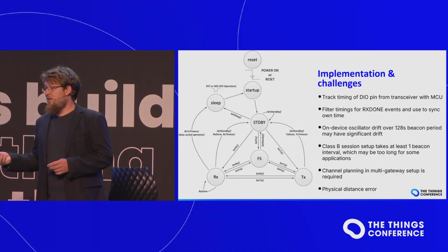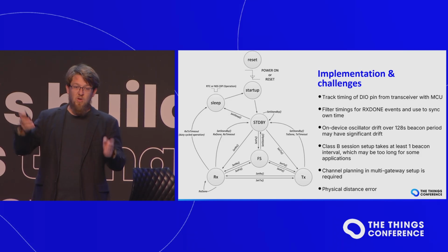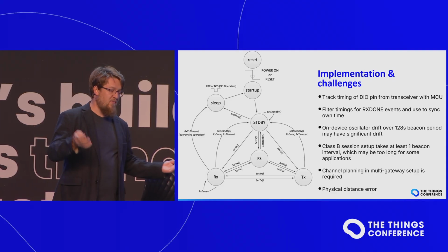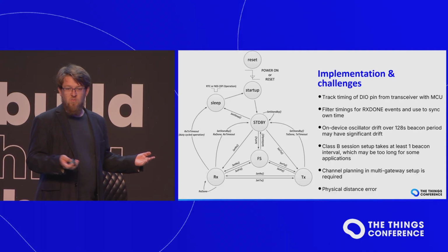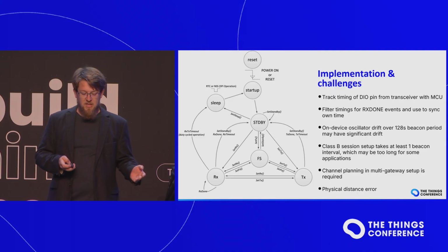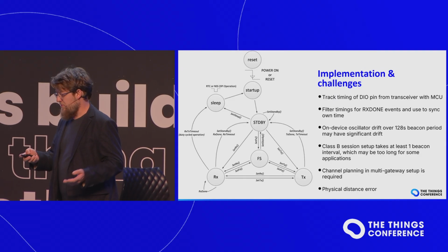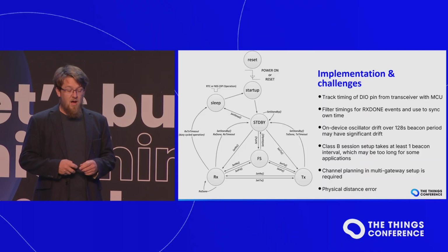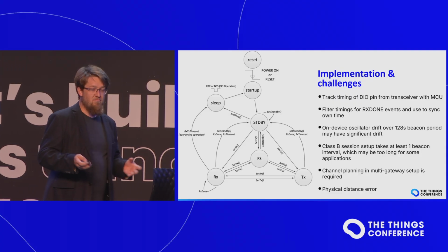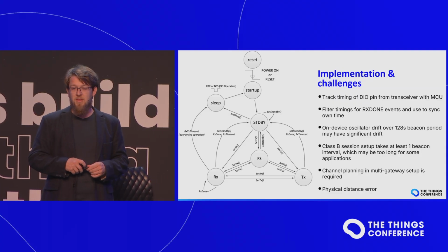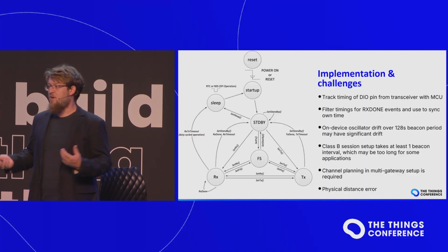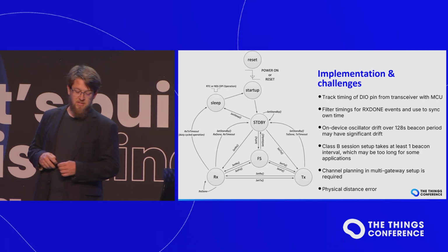And you need to keep in mind, if you have large physical distances, you need to account for the propagation delay of the actual signal between the gateway and the device. But you can use whichever positioning method to figure out where the devices are relative to the gateways, and at that point you know the precise time. So with all of this, you can take these applications or pretty much any other application you come up with, give it a precise time sync, and get a lot more value from the hardware you already have in place.